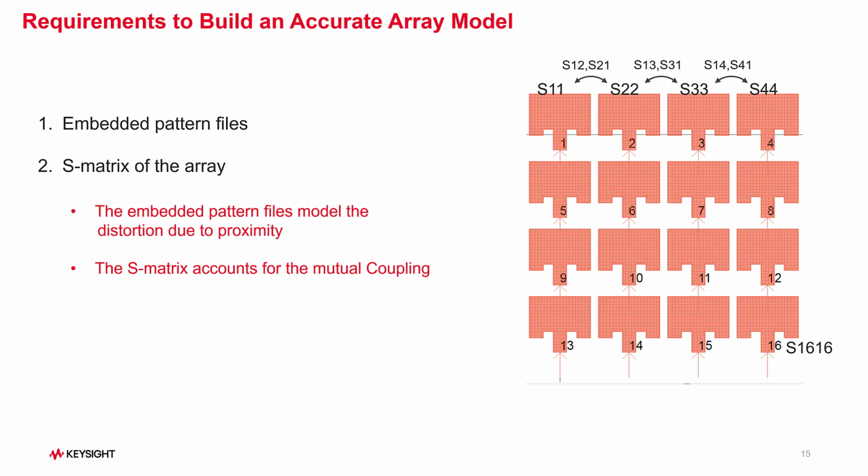If it is a finite array, if it is within the limits of the electromagnetic tool, we can capture the entire S parameter array. Otherwise, we may have to resort to other techniques to be able to scale up the S parameter file to a larger array.